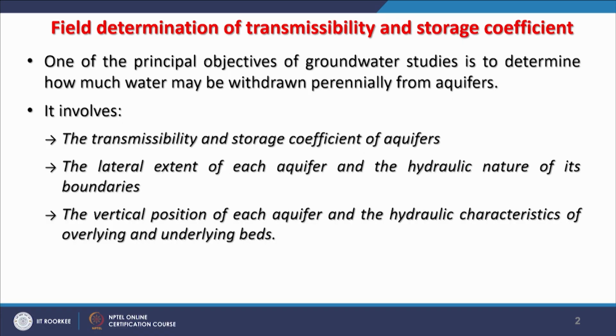After transmissibility and storage coefficient of aquifers, we need the lateral extent of aquifers and the hydraulic nature of its boundaries. Also the vertical position of the aquifer, how it is positioned in a section, and again the hydraulic characteristics of overlying and underlying beds, because we may have confined aquifer conditions. So, we must know the hydraulic characteristics of these two beds and of course the aquifer.